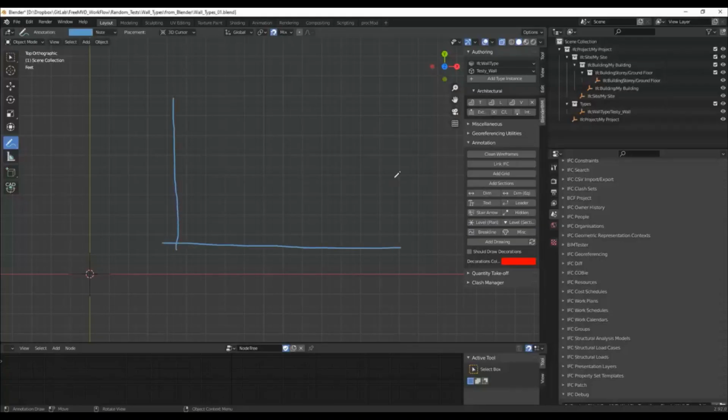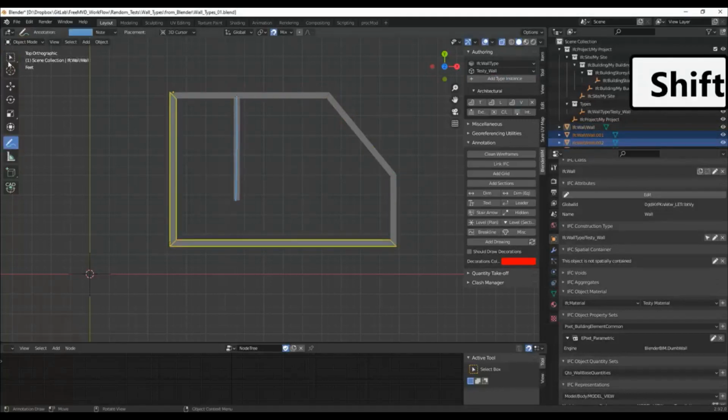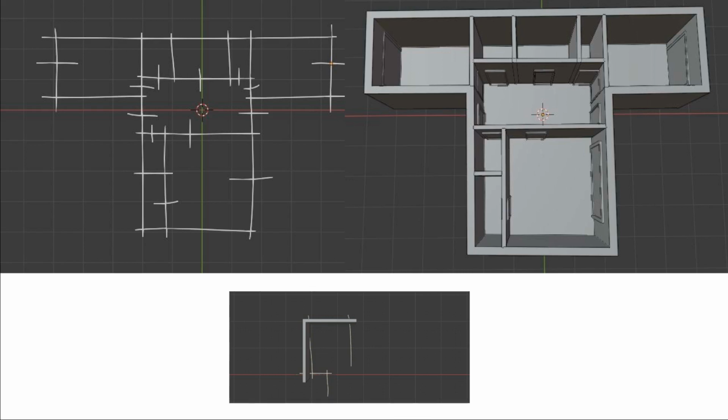Native IFC also works at the concept stage. And it's also possible to develop custom tools and custom workflows, like in this example, where you can sketch out and trace walls, which are automatically generated to real BIM walls based off wall types on the fly. This system started out as a user prototype and now works as a wall creation tool.